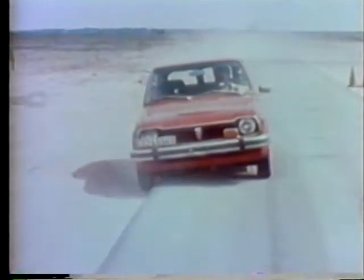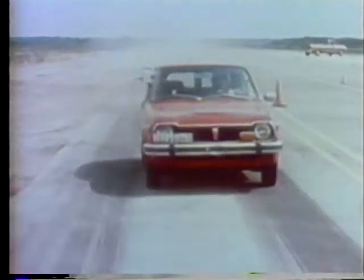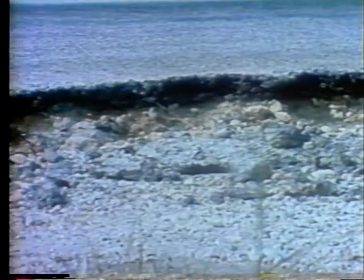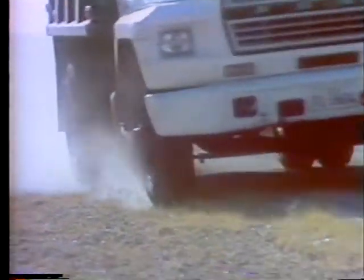Pavement edge drop-offs can cause severe vehicle handling problems and complete loss of control. Pavement edge drop-offs can occur naturally as the result of drainage, erosion, and settlement, or as the result of traffic action. This is particularly true on narrow pavements, especially when combined with high truck volumes.